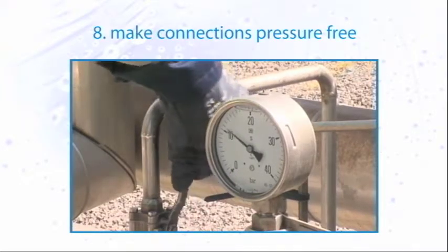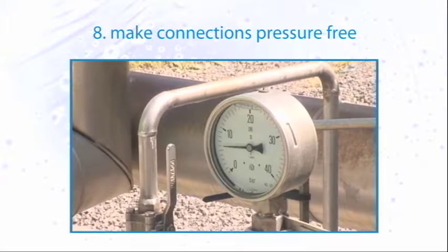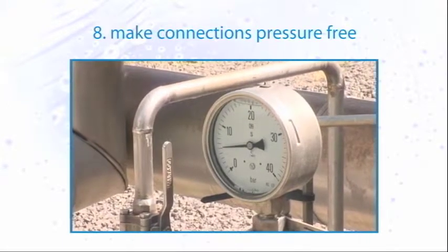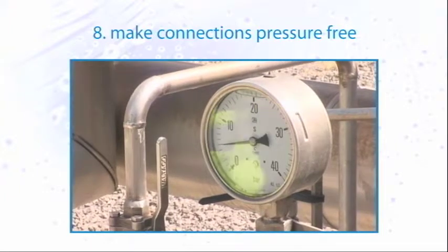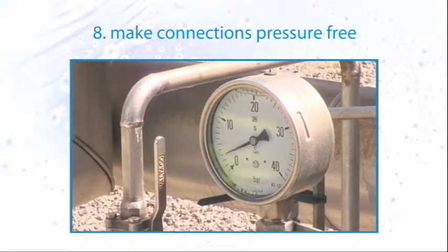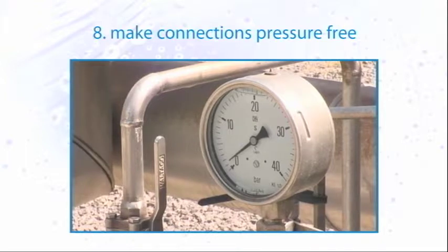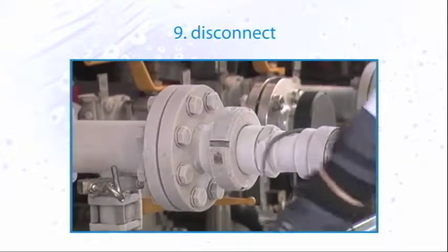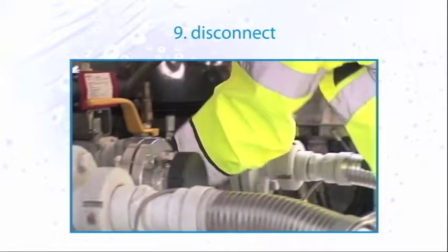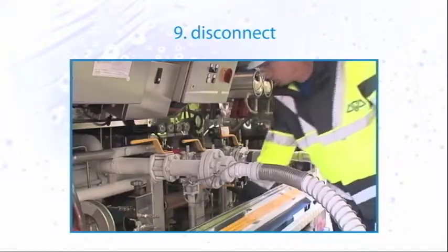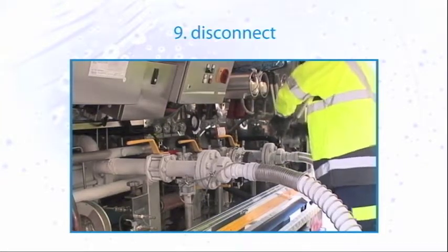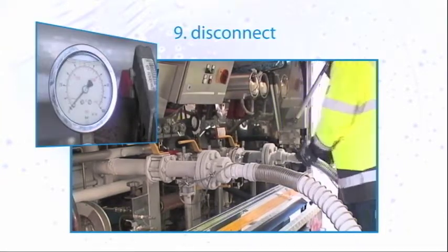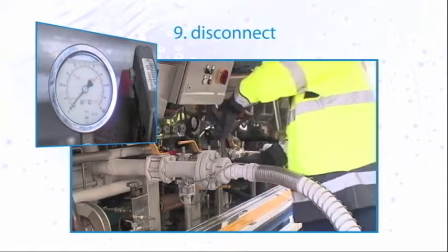Next, open the valves to the collection receptacle to free the connecting hoses of pressure. As soon as both pressure indicators show 0, and the green lamp on the control box is on, you may disconnect the connecting hoses. Also be certain to check the hose along the side of the tank lorry. The manometer there must show 0 and therefore be pressure-free.